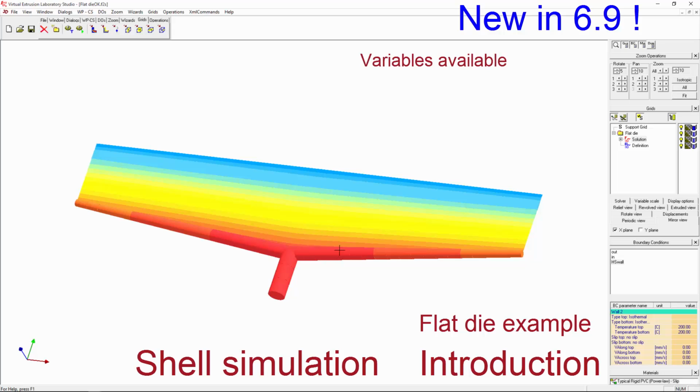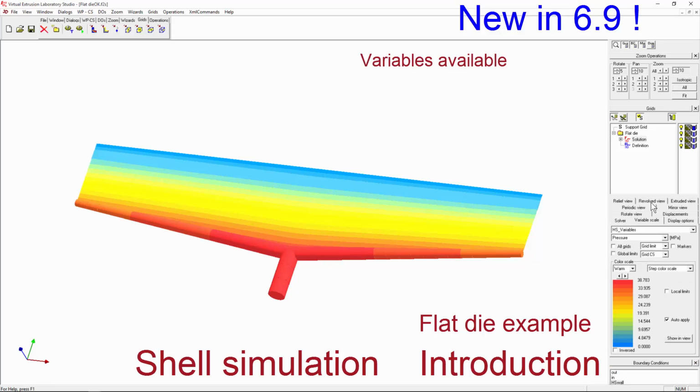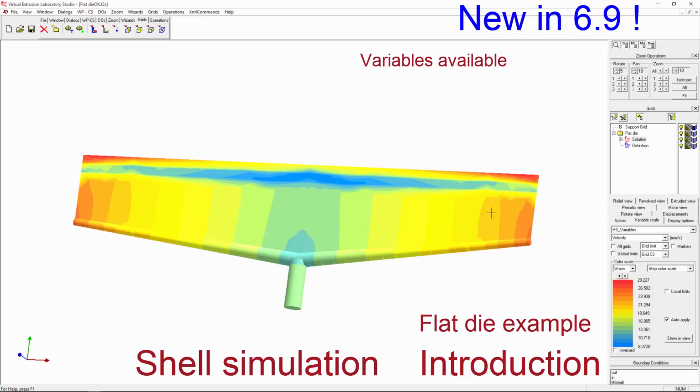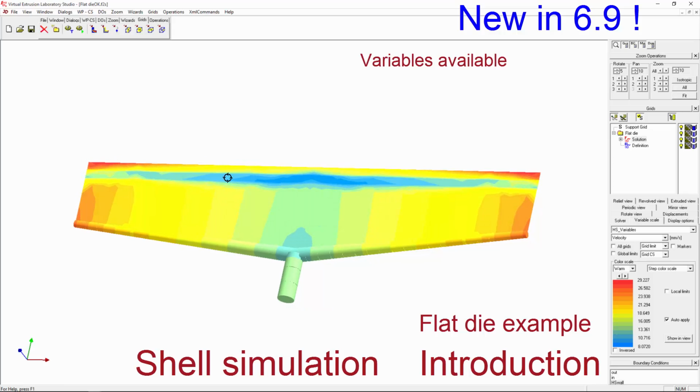We see how the polymer is flowing here. At the same time, we can look at, let's say, the average velocity, and we see the polymer having much higher speed over there, and much higher also at the lips. We see some slowing down in the relaxation chamber. Now the velocity field is a little jagged. That's because the mesh should be still refined to have a smoother solution.